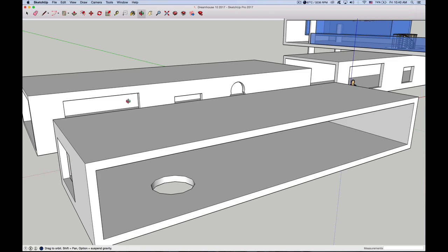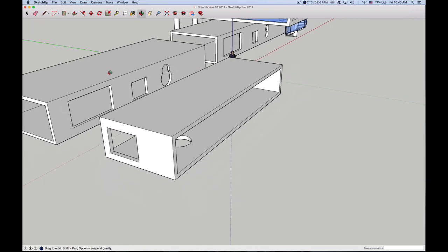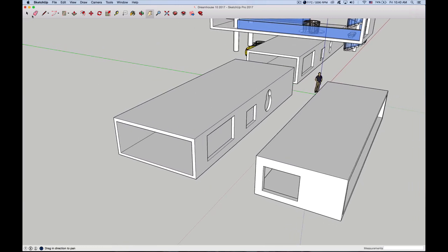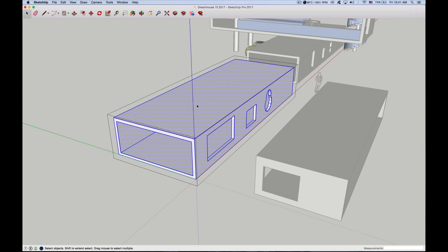Now as you can see, this floor also needs to be opened up, right? Because it will have the openings that go through. So we will make a round space also here. Okay. So in order to do that, we have to go back into the group of this box. So we double click until we see this mesh here, so that you reach that part of the model.